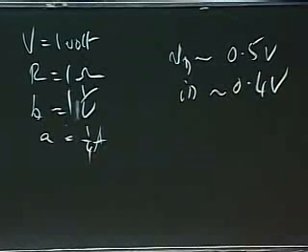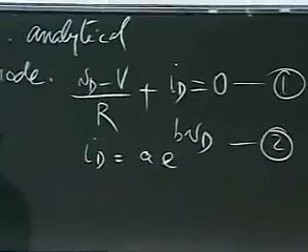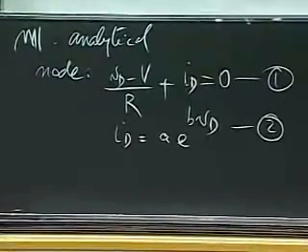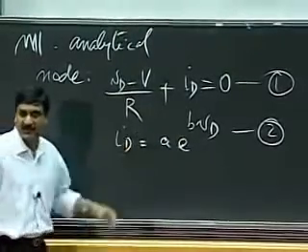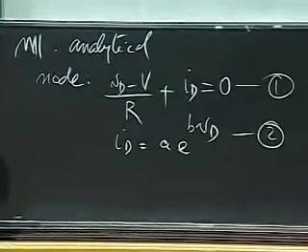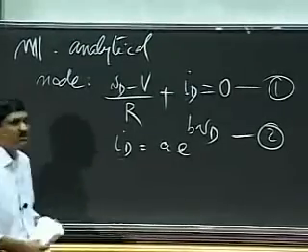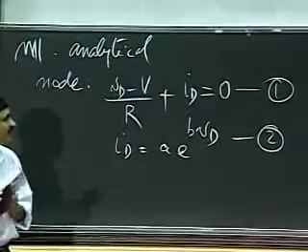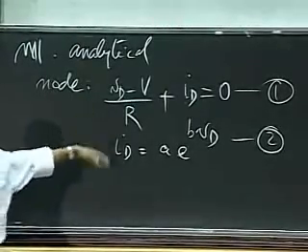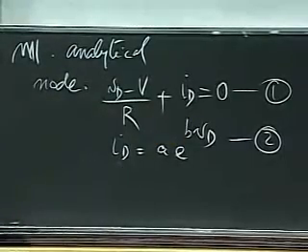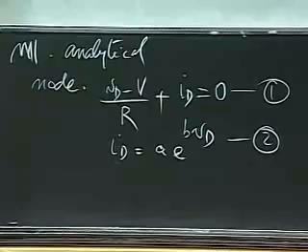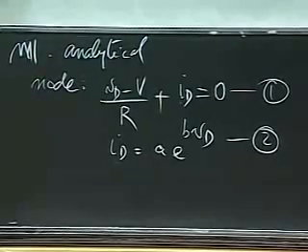In 6002, we don't dwell on working too hard to solve equations of this sort. If you cannot substitute this in here and solve it directly, we don't ask you to go and learn numerical techniques and so on to solve it. But just remember that you can use trial and error, or you can use back substitution and other techniques that you'll learn in future numerical methods classes and apply them here. For here, we can stick with trial and error if you like. For these values, VD and ID are 0.5 and approximately 0.4. We're done. It's really that simple.